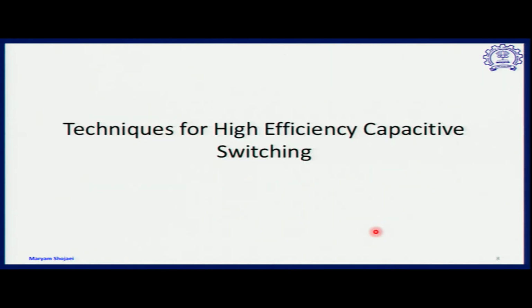So moving towards recent techniques which are reported for high efficiency capacitive switching, I want to show you how different switching schemes can change the energy consumption in the capacitive switching. That's the main focus of this paper, based on the example of pie charts we noticed in the beginning of this lecture.